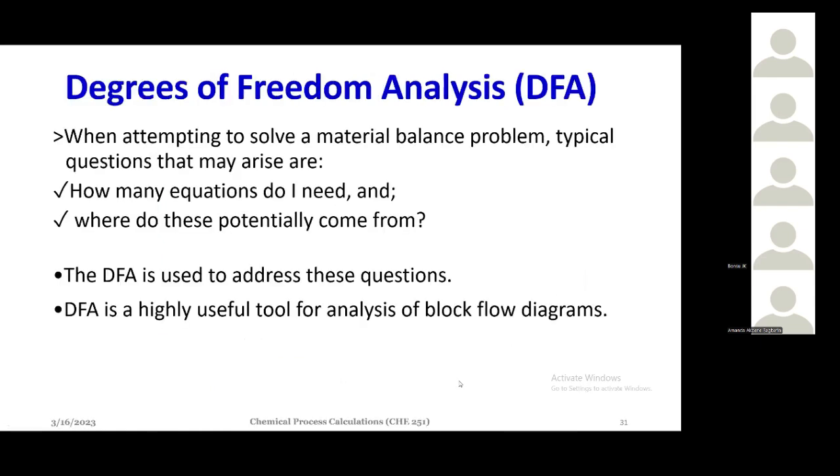This is one of the most interesting parts when it comes to material balance calculations: your degree of freedom analysis. Now, when you are trying to solve a material balance problem, there are some questions you need to ask yourself. How many equations do you need? And where are you going to get those equations from? Of course, you get those equations from your material balances, but you should know how many equations you need.